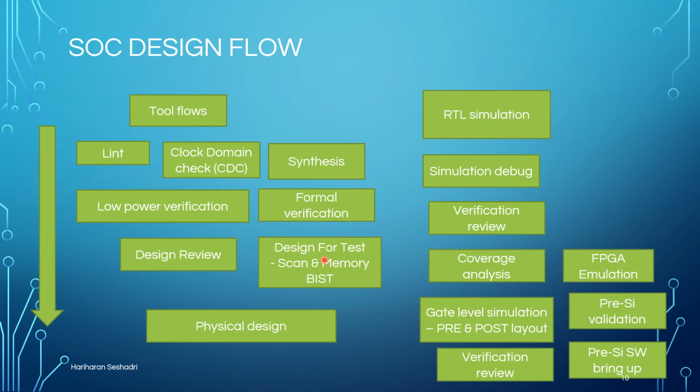There is something called design for test. So scan and memory BIST, right? It will be a separate topic, and that will be a focus of this particular course. We are going to talk about design for test. With scan and memory BIST, we have to check whether the design is testable or not. You don't want manufacturing defects, right?